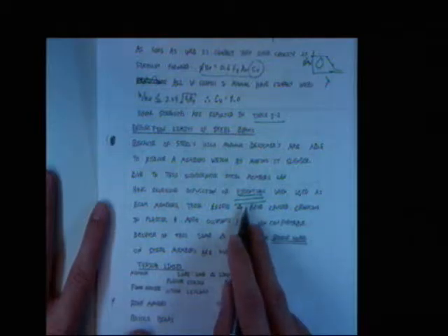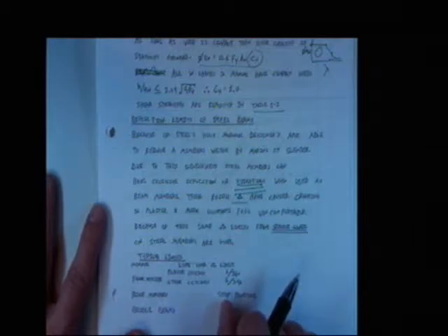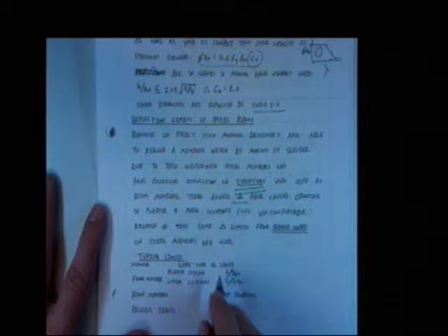Now, we don't want to do that because that's a whole semester of class that you would have to expect people that commonly just have undergraduate degrees to have to be able to design a structure. Okay? And we don't want people to have to work 3 or 4 pages of problems just to see what the deflections are. So what they did instead is they said, I'm just not going to let it deflect very much. I'm just going to make it stiff. And if you make it stiff, you often move the natural frequency away from these natural frequencies that commonly cause problems. Okay? That's why that's in there.